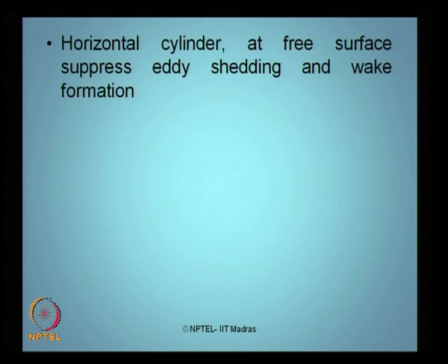Of course, in the case of a horizontal cylinder near the free surface there is a significant suppression of eddy and wake formation. Wake formation does not occur in a horizontal cylinder near the surface, whereas in a vertical cylinder it is significant. There is a suppression of the eddy formation and of course the wake region, and this happens near the free surface. So the location of the horizontal cylinder is very important as far as the vibration phenomena is concerned when you talk about fluid structure interaction for a horizontal cylinder.